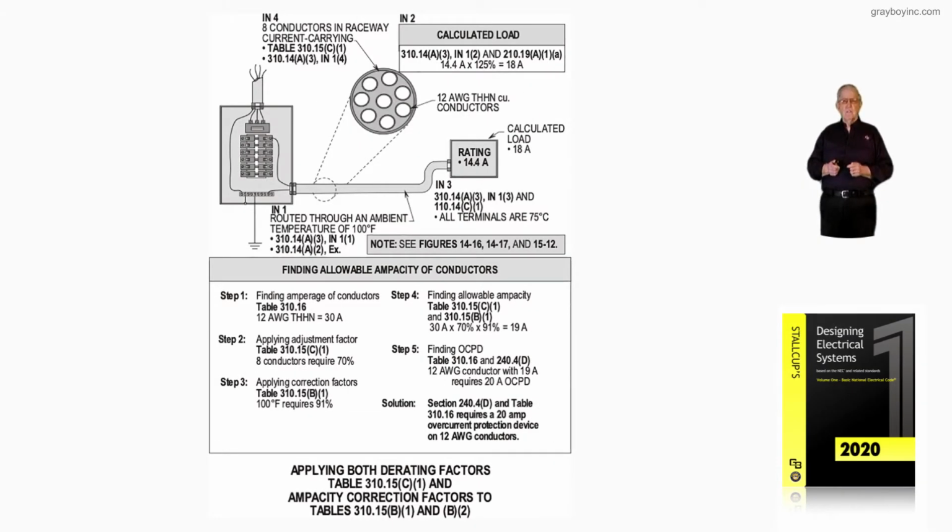Now this illustration deals with general requirements, and these requirements have to comply with 210.19(A)(1)(a) and (b). And also, you could do the same thing using the API 500, the American Petroleum Institute standard, by reviewing sections 1.1.1 and 1.1.2, if you happen to be designing this circuit in the oil field, refinery areas, production, or whatever.